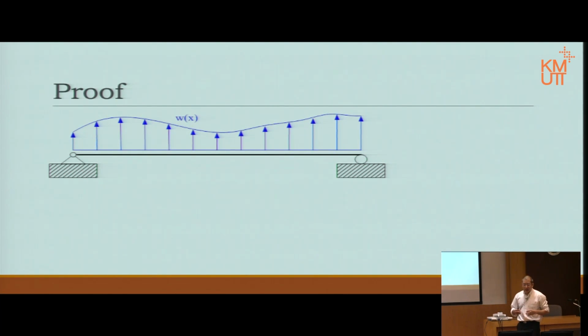Now before we continue, I need to discuss the differences between this picture and the picture in most texts. In this case, what I do is I supply upward positive. Therefore, that W, the distributed load, assuming positive, is going up. Now, in most books, you will see a different picture. The distributed load will go down. However, they will use the magnitude of minus W. So in fact, if it goes down minus W, it means just go up W. So it's the same concept, meaning upward positive.